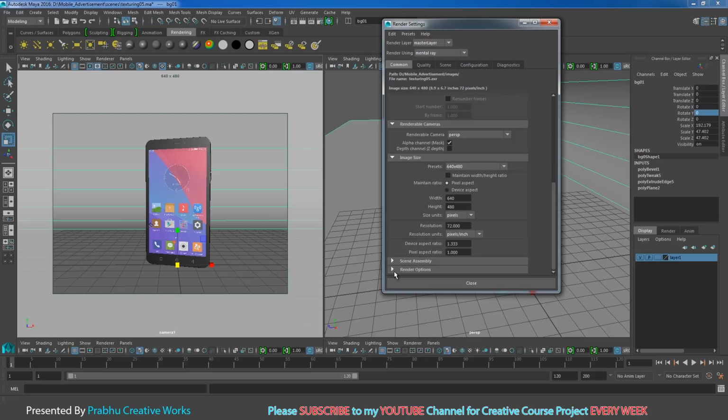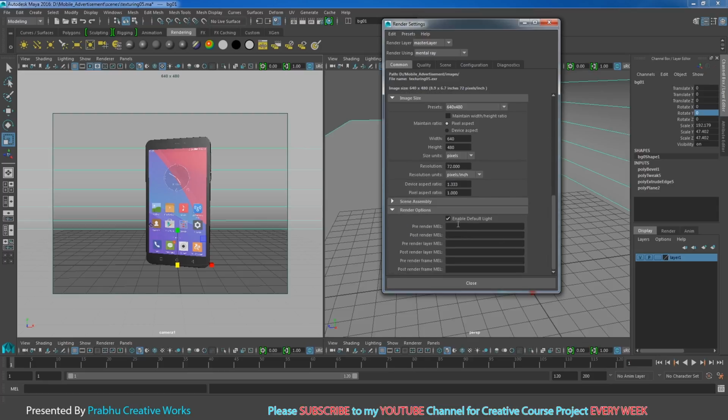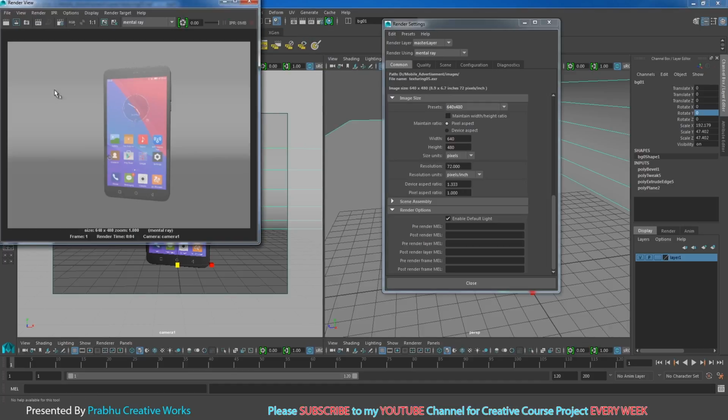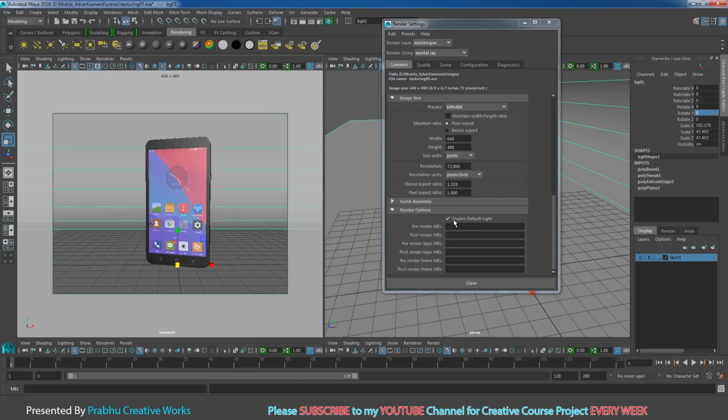So here go to render options, you want to disable the enable default light. Before that, I will click this viewport and click the render button. See here, I have not set any light in our scene, but it still shows lighting in the render, because the enable default light option is turned on. So I turn off this one.